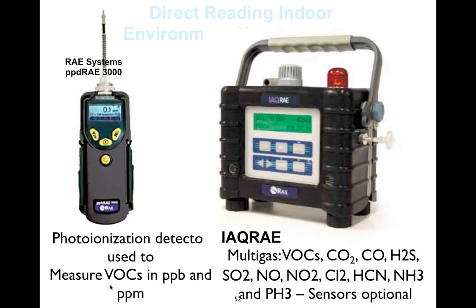We can measure and monitor those as well. There are not a lot of standards to compare to, but in general, a lot of people will say if you get over a couple of parts per million of VOCs in the air that aren't diluted, then you have to take a look at what the source of those were and whether you get enough exchange with outside air.